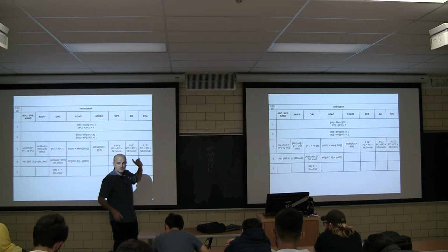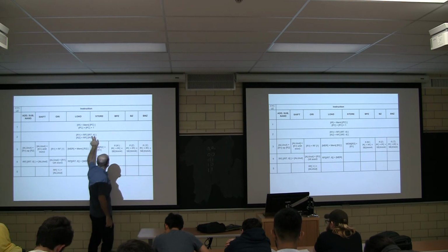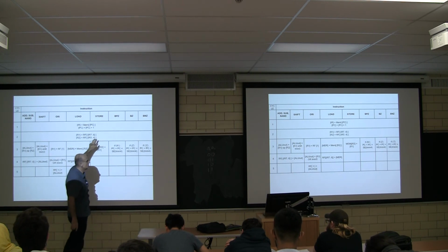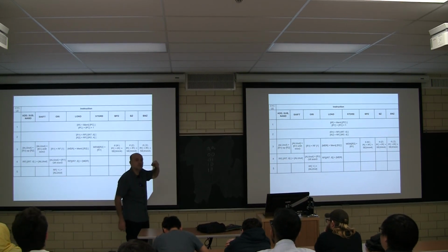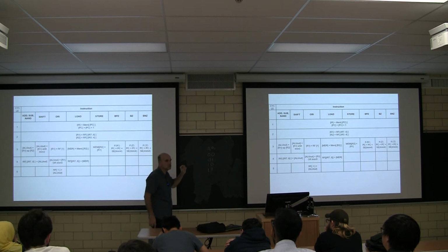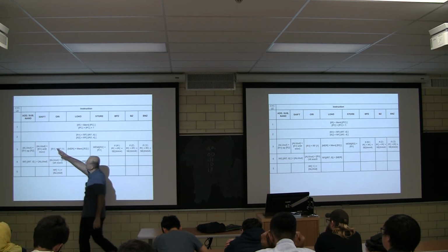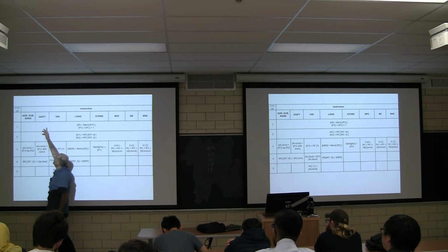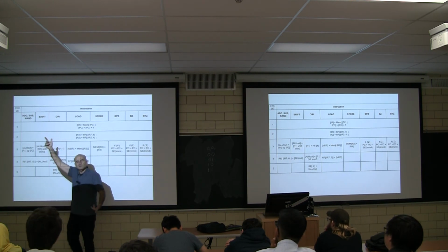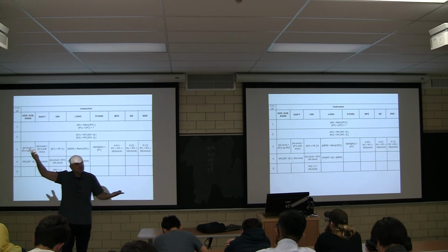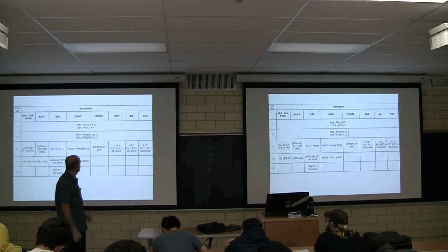We're reading 2 registers. We're using the upper 2 bits of the instruction opcode, and the next 2 bits, to read what could be, that's the key operative word, could be R1 and R2. Will these always be R1, R2? Not necessarily so. They will be for these 3 instructions, add, subtract, and AND. R1 will be useful for shift, R2 will not be. None of them will be useful for RI, okay. For load, reading R1 is not necessarily useful, but reading R2 is. And for store, both of them are useful. And for these, they're useless.